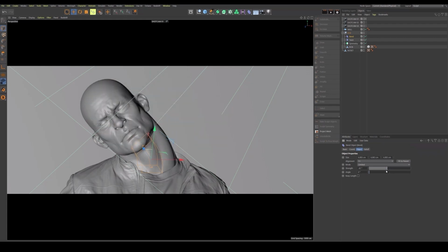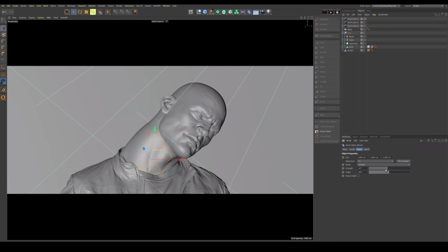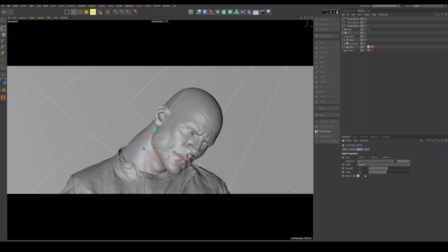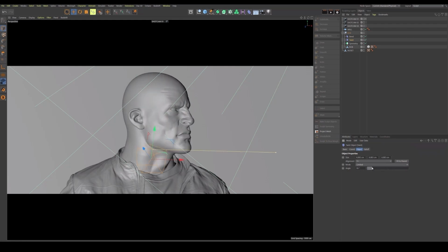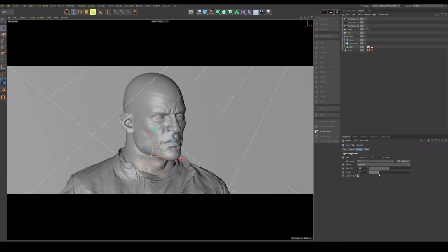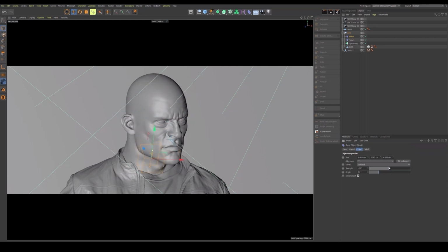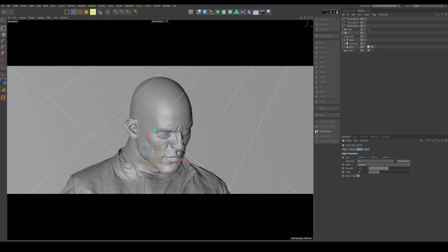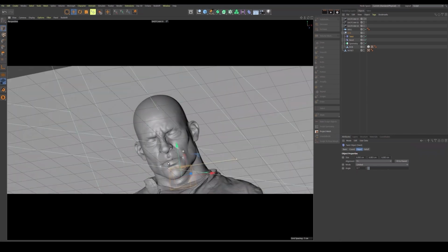So now we can adjust his neck and his head orientation. He has a very long neck because Keep Length is unchecked. So just check that, and now we can be quite subtle with our neck rotation, right? Now you can look up, you can look down, and you have to be careful about this kind of deformation, you see. So be aware of that.